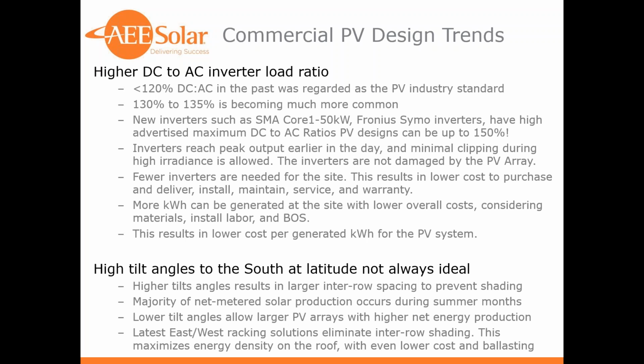This is especially the case if you carefully design either the MPPTs or the inputs and have modules facing at different planes, or using an east-west racking. If you can have half the modules facing east and half the modules facing west, the higher DC to AC ratios are definitely applicable here. And in that case, you probably would not see much clipping at all.